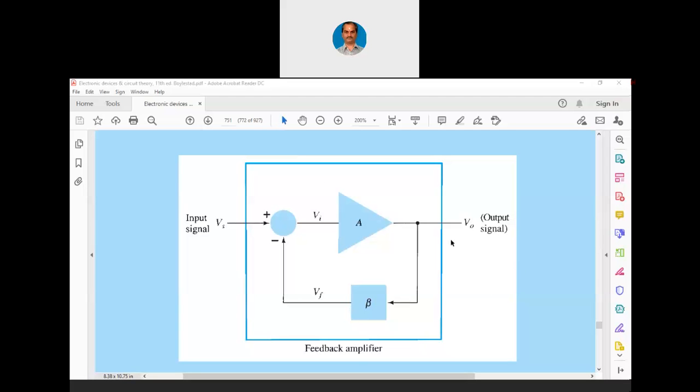Now, when you put a bubble here, you show it as an inverter. In digital electronic circuits, you always write an inverter with the triangle and the bubble. What does it mean? An inverter is nothing but an amplifier with logic states of 0 and 1. If you use the amplifier exactly in the active region, in the middle of the load line, which we also call the quiescent point, it works as an amplifier.